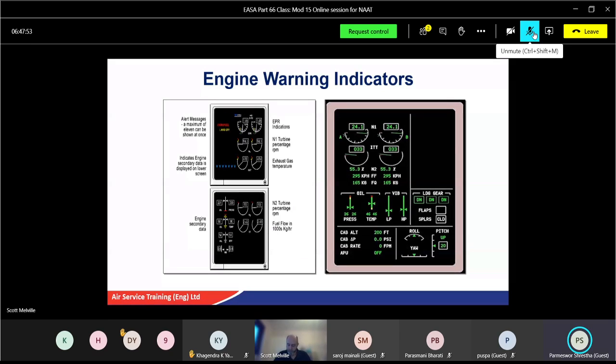On a speed probe phonic wheel, if the tooth has just gone past the sensor, what voltage will I get? Maximum negative voltage, we're coming down the slope again. Good. And if the tooth has just come up to the sensor, what do we get? Maximum positive voltage. If the sensor's directly opposite the tooth? Zero volts. And if the sensor's in between two teeth? Zero volts. Good.